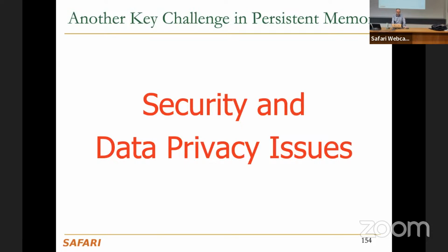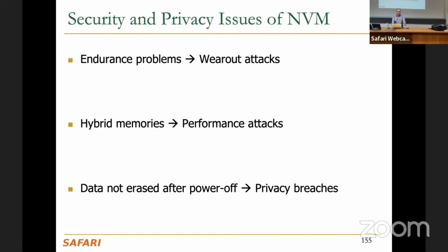Now we reach the security and data privacy issue that your colleague actually brought up. Essentially in NVM, we have these security and privacy issues. First of all, with endurance problems, we have wear-out attacks. People can design attacks to cause your chip to wear out quickly. For example, an attacker can issue a lot of writes to your PCM main memory, and that can cause that chip to wear out.